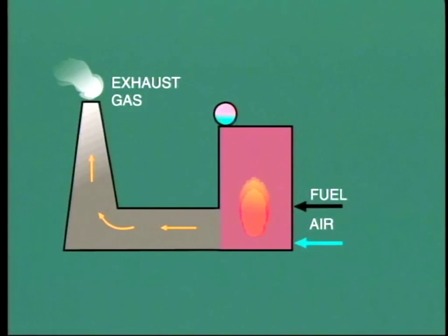We've already mentioned that some heat loss is involved if we provide insufficient air for complete combustion. But we must also pay a penalty if we provide too much excess air. Now, why is this? Well, all of the combustion gas which leaves the chimney and exhausts to atmosphere carries with it a certain amount of heat. The temperature of this gas is usually about 300 degrees Fahrenheit.